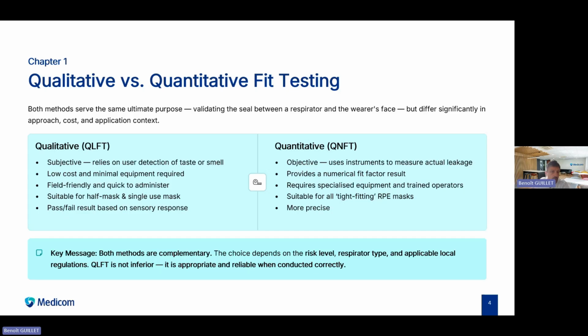The advantages of qualitative fit testing are low cost, portability, simplicity, and ease of use in the field. For the quantitative fit testing, we need to use an instrument to measure actual leakage and provide a numerical factor, in fact. So that means that the quantitative fit testing is more precise, but also requires more equipment and operator expertise.